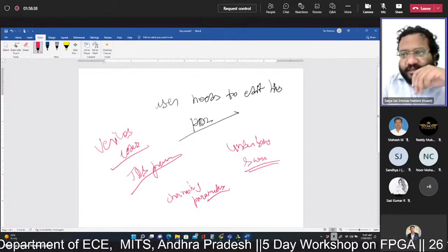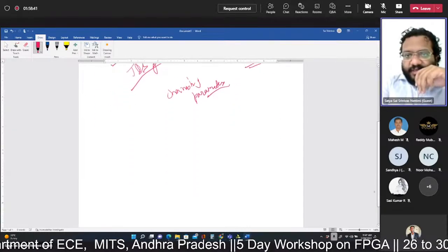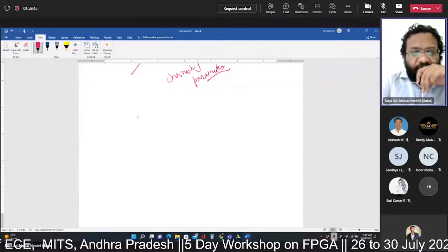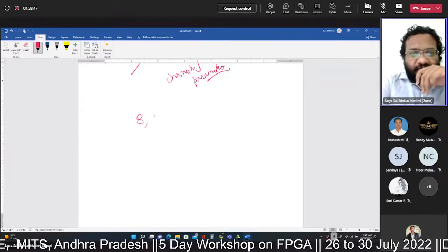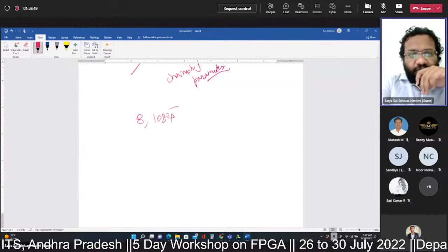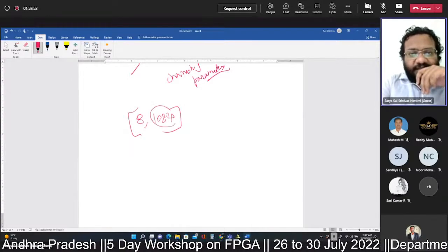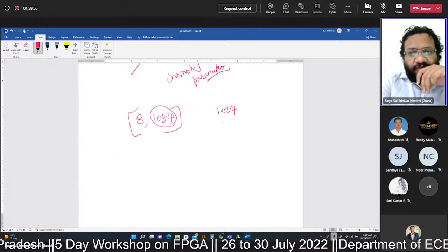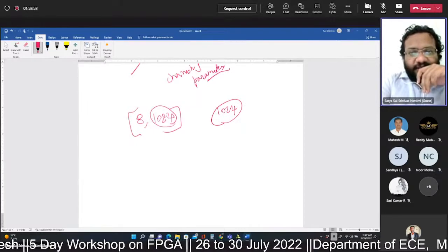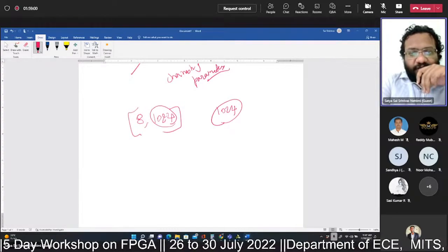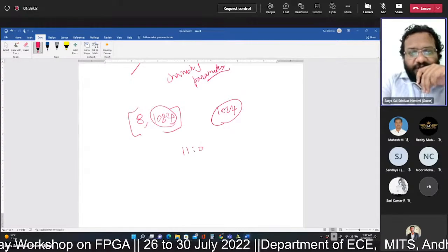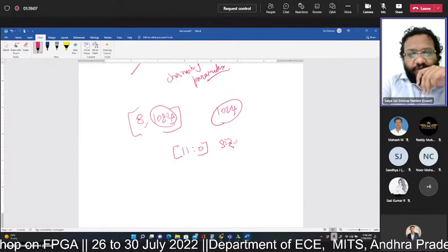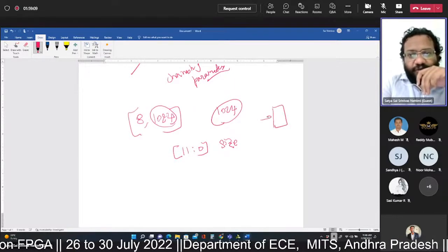Parameters in the sense, for example, the same design we have taken, frame energy, we designed to calculate up to a signal with a maximum of 1024 samples. To represent the frame size, we took an input of 11 down to 0; we have hardwired the size input that is going to our module.